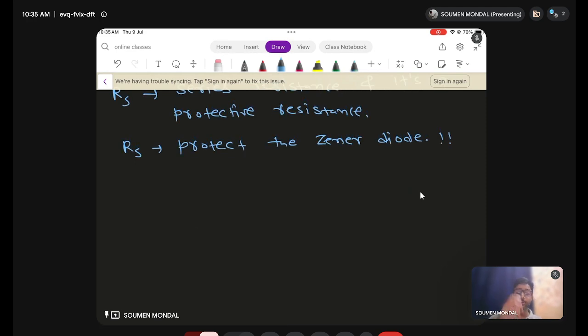If you are going to buy a Zener diode in the market, they will usually ask two things. What is the Zener breakdown voltage of the Zener diode? So let's say 6 volt, but immediately they will ask what is the power of the Zener diode. In the market we can get 1 watt, quarter watt, half watt, even 2 to up to 5 watts Zener diodes. The larger the watt, the bigger the size will be, basically a bigger and bigger cylinder. You can think like that.